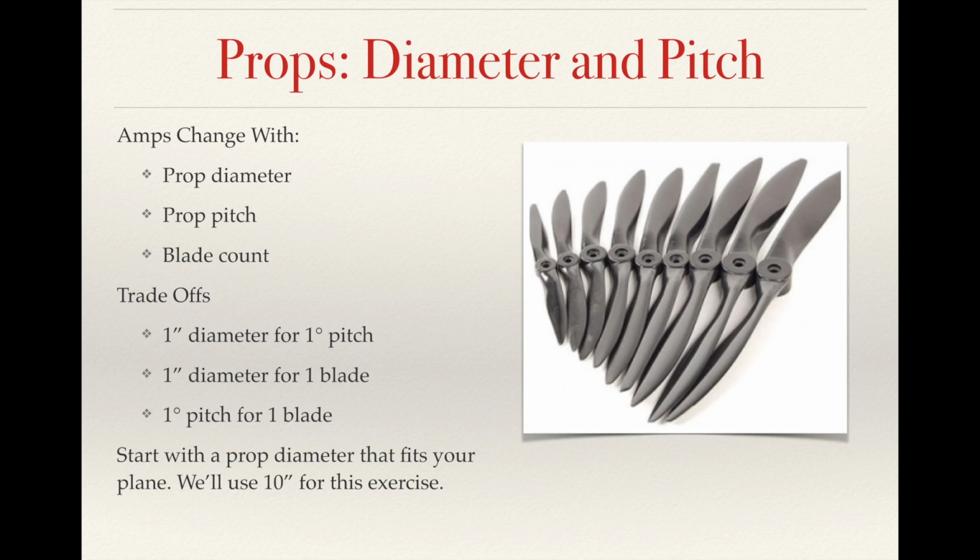So if you're flying a 2-bladed prop and you decide I'd like to have a 3-bladed prop, you could go from say a 10-inch diameter 2-blade to a 9-inch diameter 3-blade. And then the same for pitch. You can trade a degree of pitch for a blade as well.